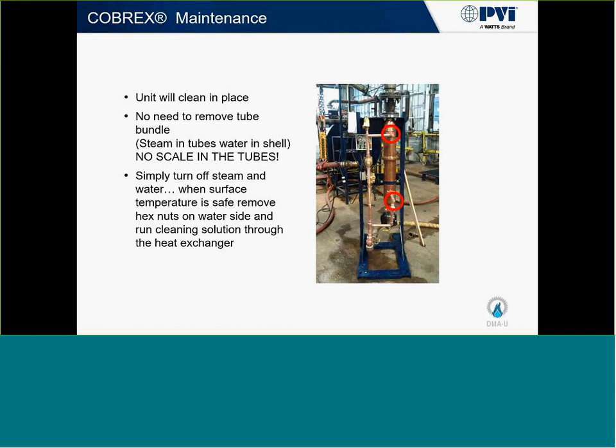In that case, you remove that anti-scale pump and the anti-scale fluid, flush it out, get it filled back up with water, turn on the steam, click on the unit, and you're back making hot water again. So instead of taking an entire day, it can take anywhere from half an hour to an hour, and all you're doing for the majority of that time is just waiting for the pump and the anti-scale solution to do its job.